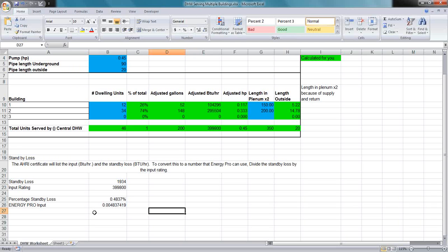I think that's hard to do unless the building is operating and you maybe trend that information over a good period of time to figure out what that brake horsepower is. Doing it as a one-time deal when you get out on the job site and say, this is what the brake horsepower is, that's probably not very accurate because you don't know what kind of conditions that pump's operating at.